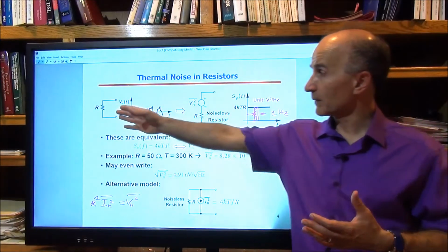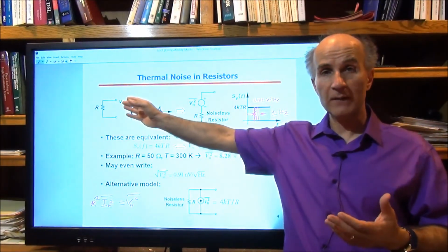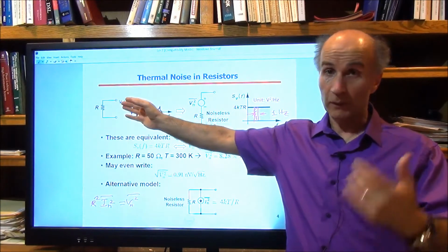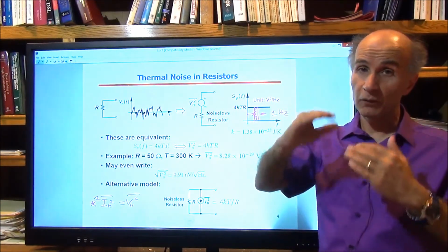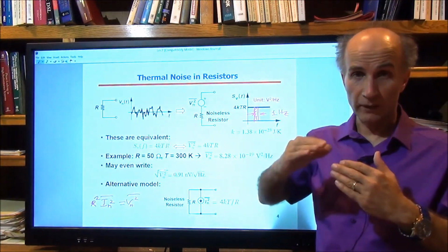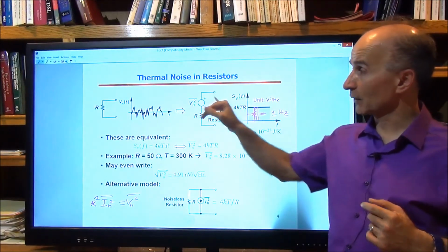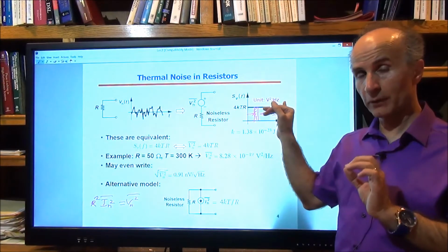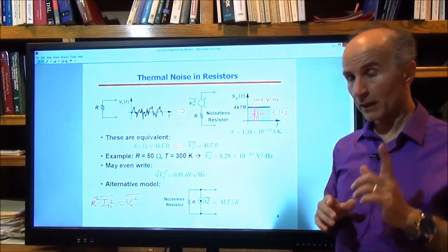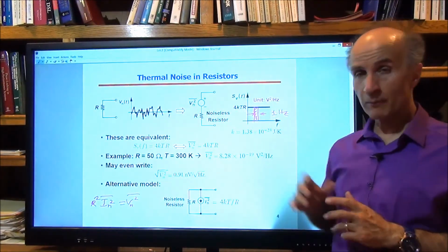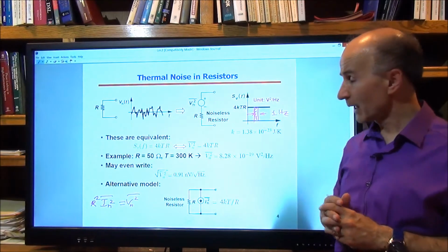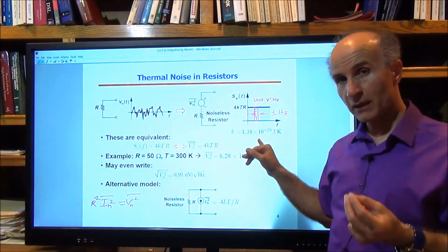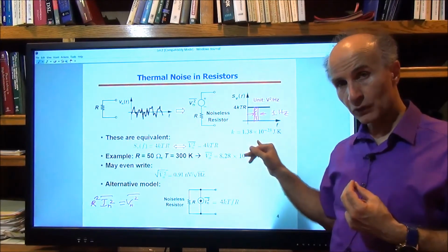For example, if this resistor drives the gate of a MOSFET at low frequencies, it doesn't deliver any power, but we are still interested in the noise voltage that it generates. So we are looking at the spectrum of a voltage quantity, and the result is volts squared per hertz. Number two, k is Boltzmann's constant and is given by 1.38 times 10 to the minus 23 joules per Kelvin. It's good to memorize this number.